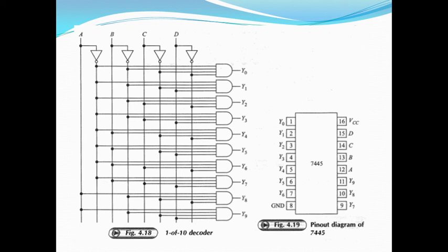Pin numbers 12, 13, 14 and 15 are nothing but the BCD inputs. Pin numbers 1 to 7 and pin numbers 9 to 11 are nothing but the outputs Y0 to Y9.